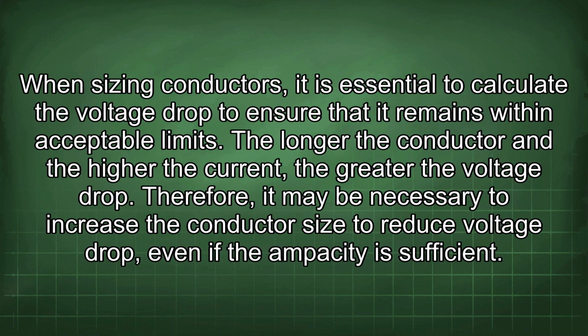When sizing conductors, it is essential to calculate the voltage drop to ensure that it remains within acceptable limits. The longer the conductor and the higher the current, the greater the voltage drop. Therefore, it may be necessary to increase the conductor size to reduce voltage drop, even if the ampacity is sufficient.